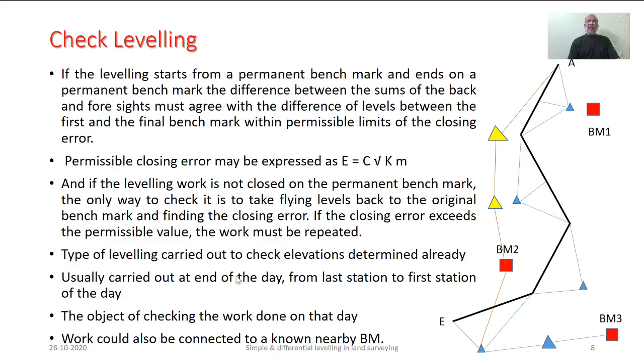One more thing is, say if you have certain benchmarks such as BM3, BM2, etc., of which the reduced level with reference to the work that we have carried out is already in our hand. Hence, instead of going to the starting station, we can redetermine the reduced level of BM3 and BM2.